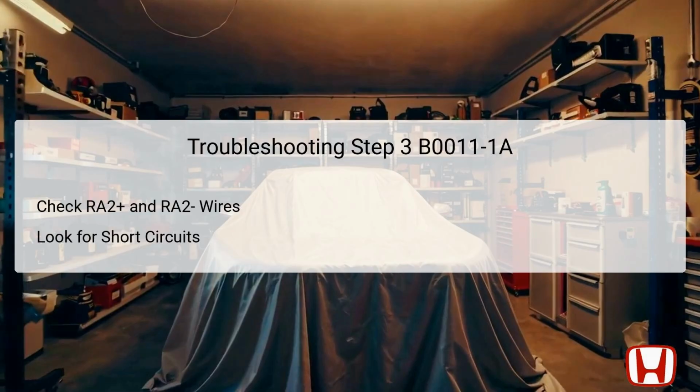The expected norm is that there should be more than 1 megaohm of resistance, indicating no short circuits. If the resistance is lower, a fault exists in the circuit, and further tracing of the wiring is necessary to locate the specific short. The final troubleshooting step involves inspecting the SRS unit itself, if previous tests have indicated normal operation for both the front passenger's airbag and the wiring.